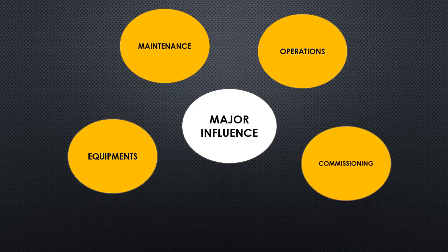And the fourth one is about commissioning. Commissioning is a stage after the construction. Once you hand over the project to the client, they start up the whole system. So you may require vents, drains, and such items in the piping design. So the piping designer should consider the provision of vents and drains during the designing stage.